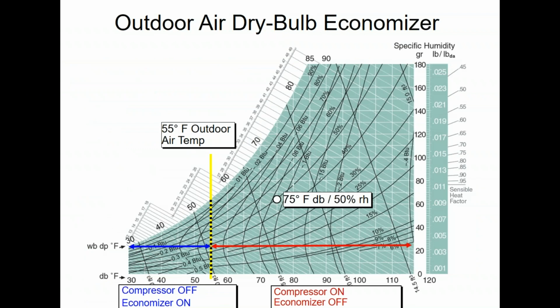Look at those on the psychrometric chart, and I'm assuming most of you guys have seen psychrometric charts before. Just a quickie refresher. These numbers on the bottom axis are dry bulb temperatures. On this axis over here on the right-hand side, that is absolute humidity, actual real moisture molecules, or grains of moisture, if you will, right? And these curved lines right here, let me get my little 60% relative humidity, 40% relative humidity. They're curved, right? Humidity is relative to both temperature and moisture content, so they are curved lines. And then obviously this line right here is 100% humidity, and there's no chart on the left over here because we never have more than 100% humidity, at least for HVAC systems.